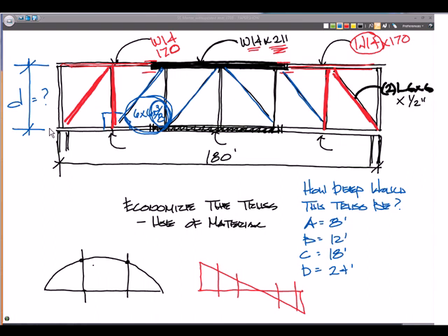All right, so the answer that I would go with, and I'll give you this rule of thumb on the exam, and Sid's got the answer that the deepest one probably works, but may not be the most economical. I would go with 18 feet on this, okay? And I'll show you where we can get some of these rules of thumb, that the span to depth ratio would be about L over 10. So if we know the span is 180 feet, just divide it by 10, and it's approximately 18 feet deep. You could maybe get down to 16. You may go up to 20 depending on the loads and what you do.